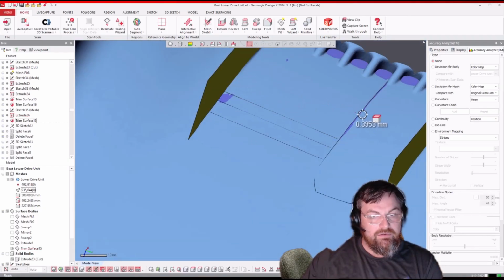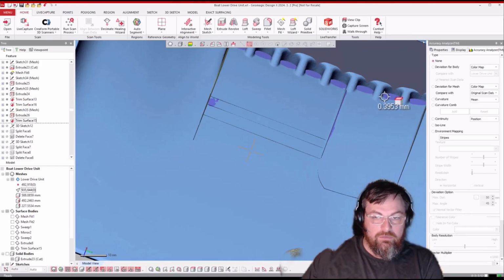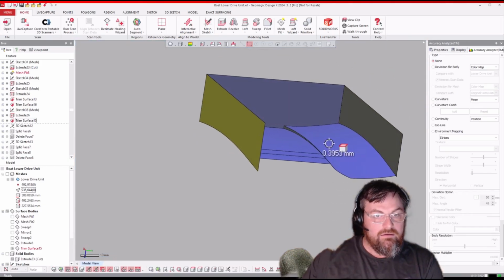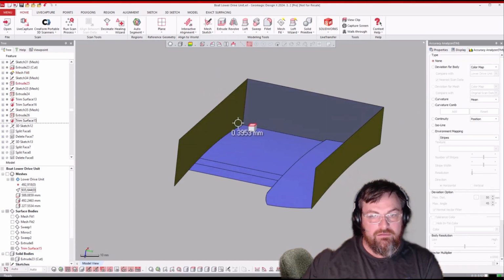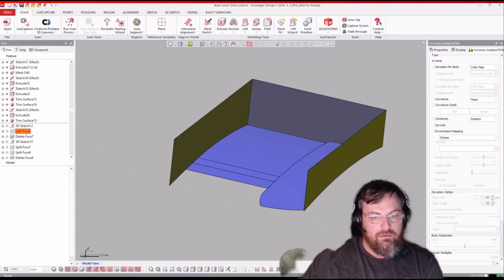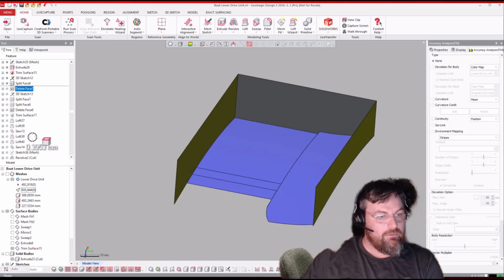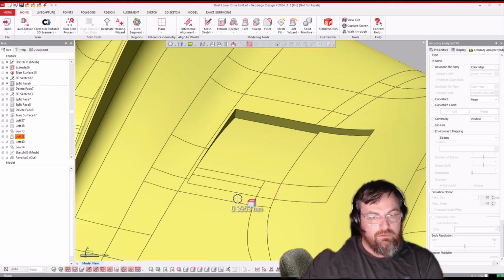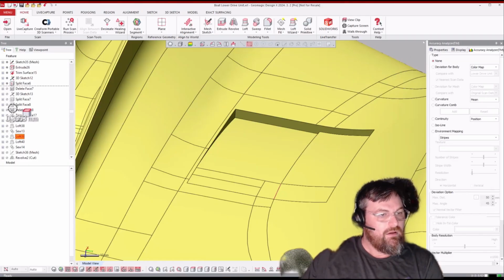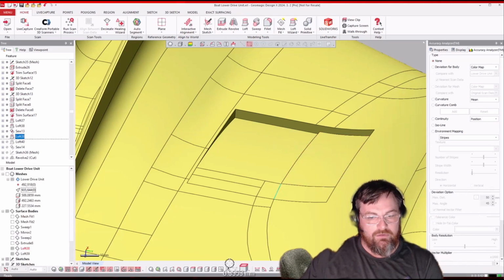They went ahead and did a surface extrude there. They created a vertical surface here and then trimmed it all together. So if I hide it, you see that fit, trim, all this together. Let's just keep going forward and see what they do here. Okay, went ahead and trim it all together. So they deleted a face, created a surface, and then did this surface trim all together here.